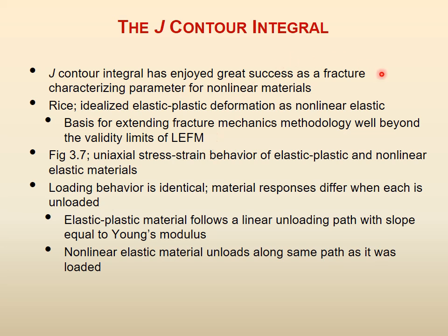So the curve is there, but it is elastic in the assumption that everything can go back to zero deformation. You take a normal elastic plastic stress-strain curve, and assume one extra thing: you don't go back on a straight line parallel to the initial straight line, you go back entirely on the same curve. This is called non-linear elastic. Rubbers and polymers are like this. So we take all the calculations for the metal, but assume non-linear elastic behavior.